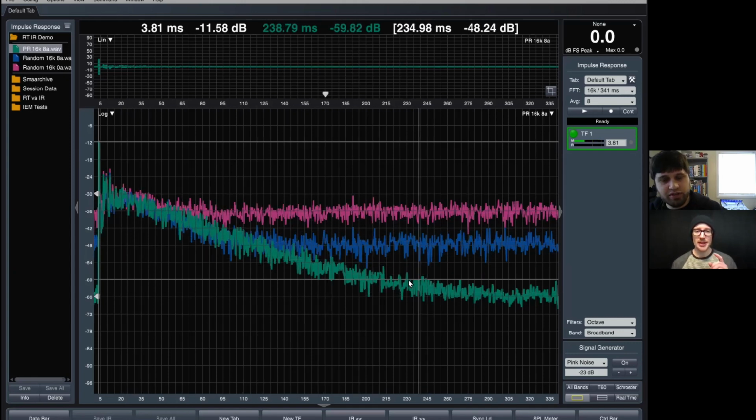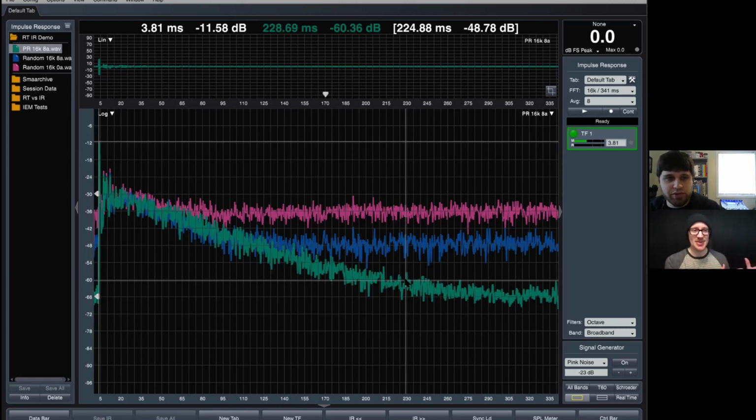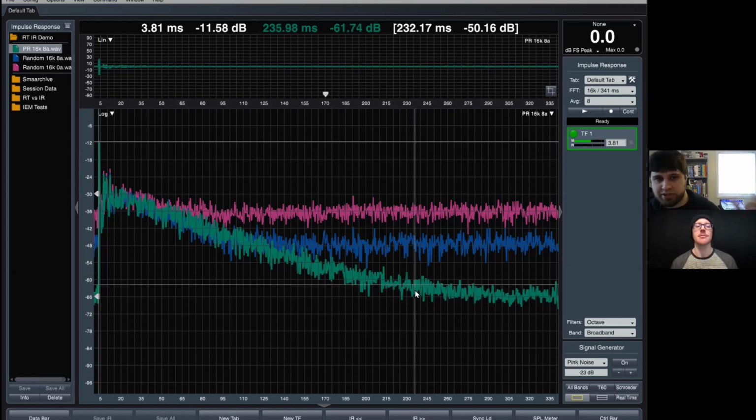That's cool. Remind me, why do we want to lower the noise floor? I think maybe we covered this at the beginning, but at this point I've forgotten. Well, we may or may not want to, right? If we're going to finish up by comparing the frequency responses of these to the real-time measurement, we'll see that they're going to be pretty much the same. So again, if you're just measuring because you want to EQ your PA, you don't need to bother with lowering the noise floor, because that stuff happens way up on the top. Our world is the top 10 dB when we're not EQing stuff that's 70 dB down.